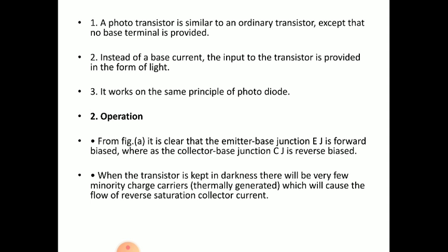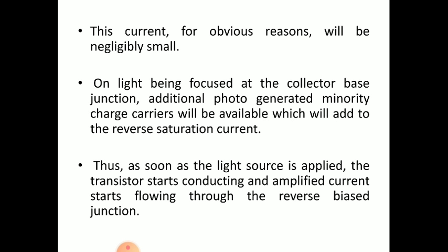So when it is in darkness, that is no input light, no heat, no electron-hole pair, and no current. Then a small reverse leakage, the saturation current, will flow. This current, for obvious reasons, will be negligibly small. It is also called dark current.